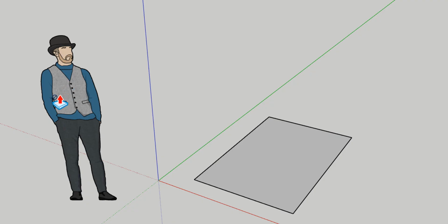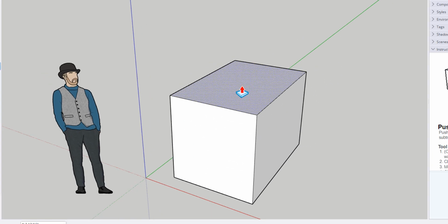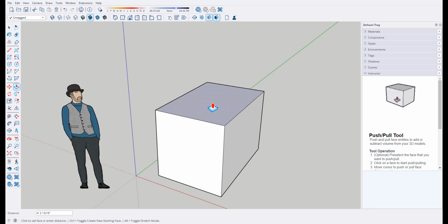And we'll talk more about that. This person is a component made up of different surfaces. So you can't push-pull a component. Again, we'll touch back on that later in the semester. But this we can. So let's say I want it to be 4.5 feet tall. So click to start. And now I'm going to move my mouse. I'm not dragging. In other words, this is one of the times I said, do not try to click and drag. You won't be as accurate.